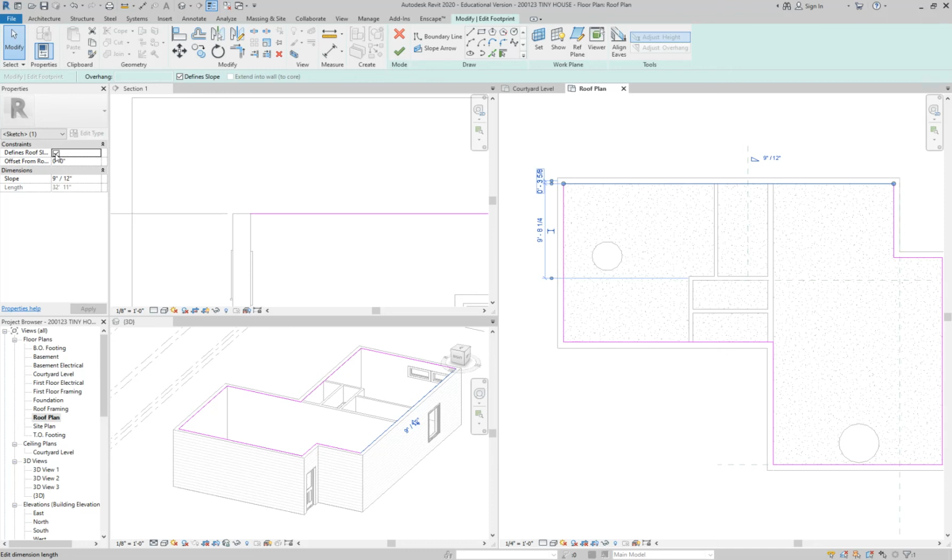Oh, okay, so double click on your roof for me, because we want to edit it. So you have to click on the line. I know it sounds weird. There you go. So now you see the triangle. Now do the hover, tab, click to grab the whole roof. Hover one below, tab, and now click.